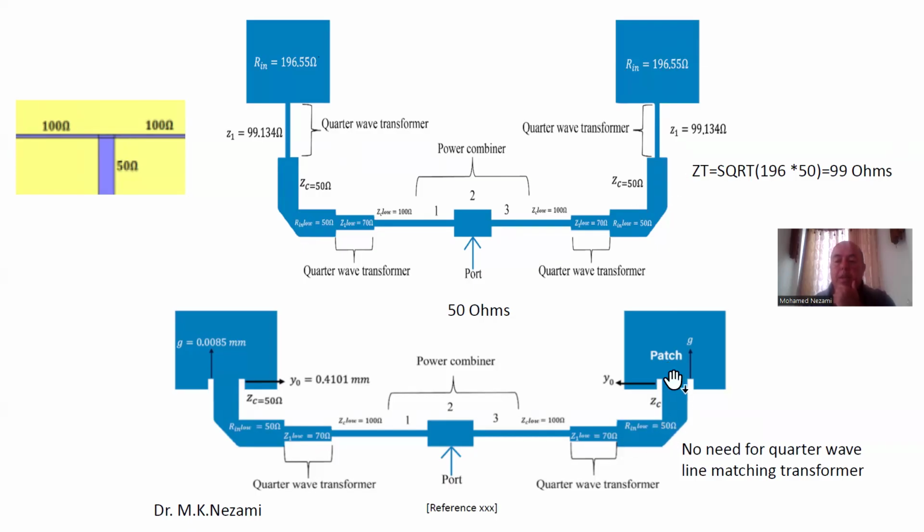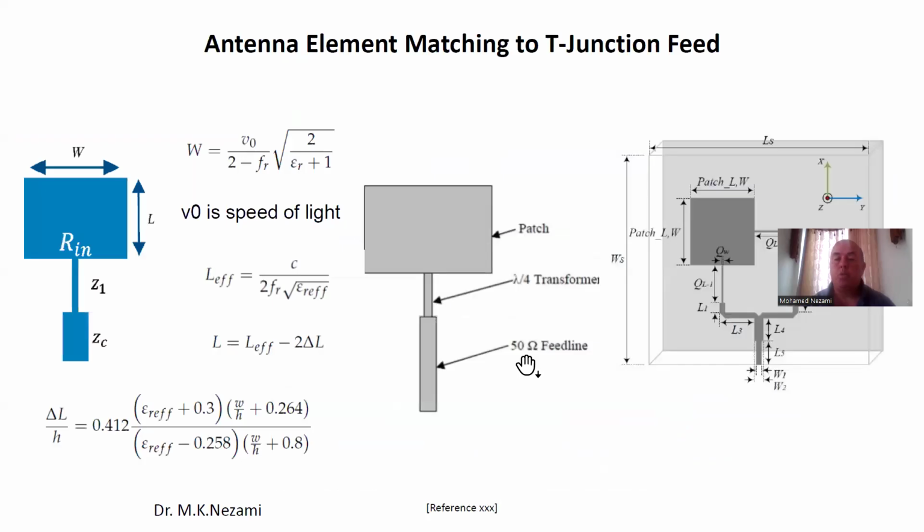While this type of antenna here, we have these inlets in here that you can vary, the gap width and the depth of this slit, and actually make this antenna 50 ohm. If you do that, then you obviously don't need any transformation in between, and that simplifies the antenna feed network. That's why, if you have an antenna array feed designer and an antenna aperture designer, you need to have them at least interact at the beginning so that you can reduce the complexity of the feed network.